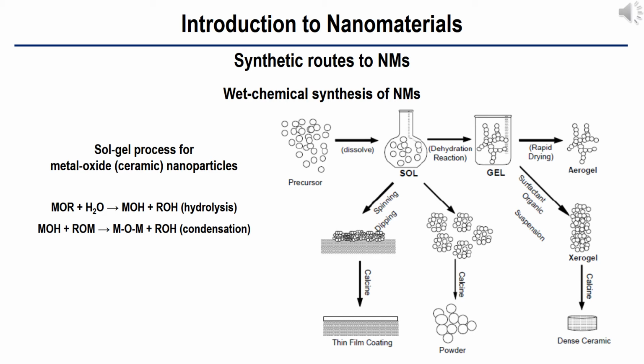This process is complicated due to fundamental changes in the structure of the gel. The drying process has itself been broken into 4 distinct steps: first, the constant rate period; second, the critical point; third, the falling rate period; fourth, the second falling rate period. If isolated by thermal evaporation, the resulting monolith is termed a xerogel. If the solvent such as water is extracted under supercritical or near supercritical conditions, the product is an aerogel.